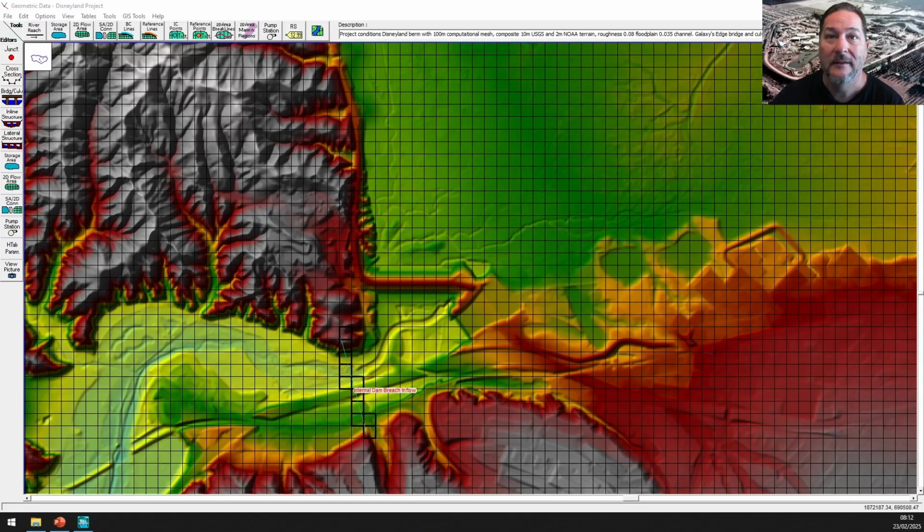breach hydrograph. Now we don't need to worry about the energy gradient here because even though you can enter that with the flow data, it won't actually get used as I understand things. The documentation does warn about some potential double routing if you don't use a cross section like we've done here. So be sure to have a look at that if you use any other alignments for your internal BC lines. I'll link to that below.